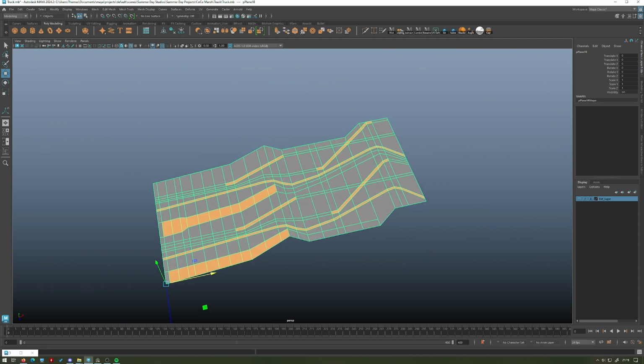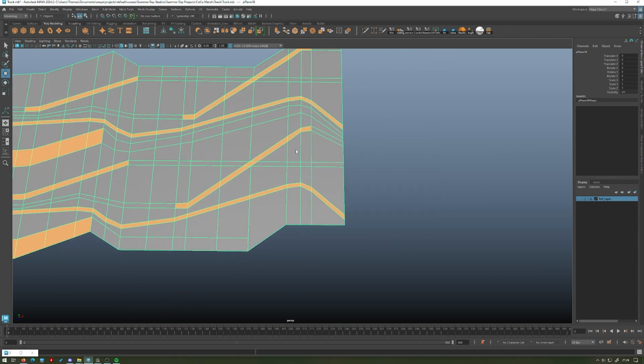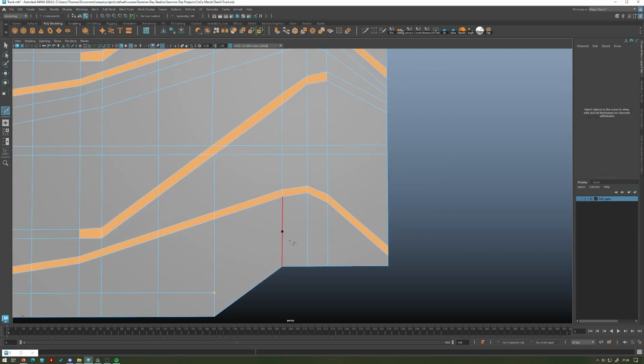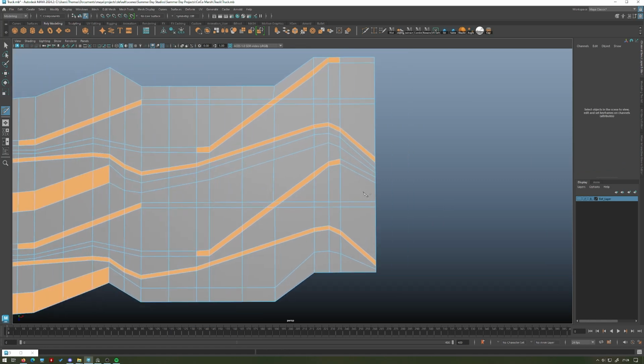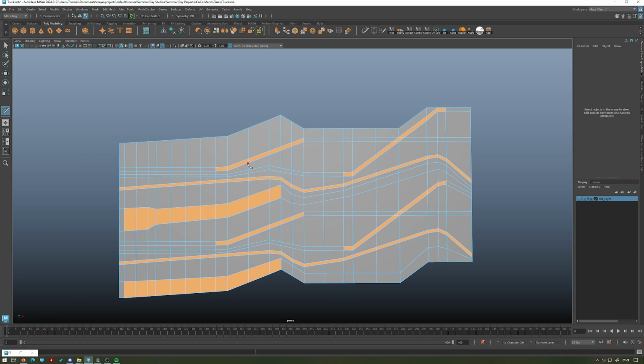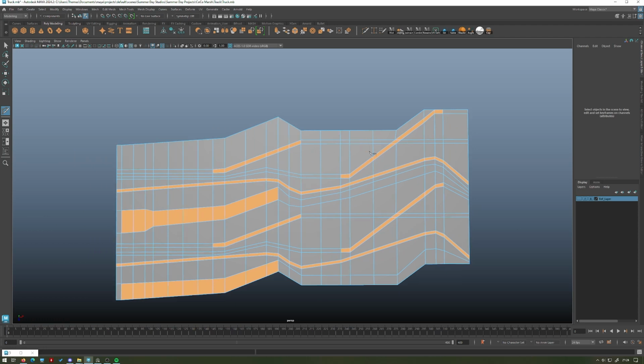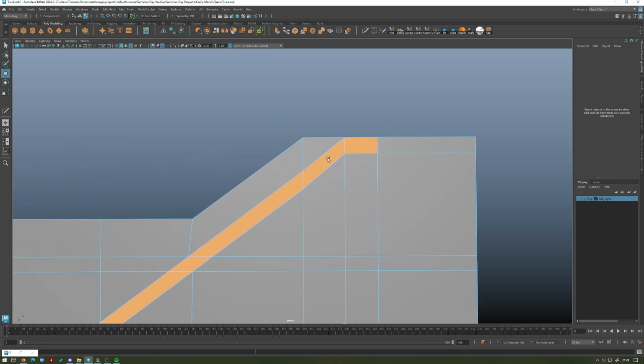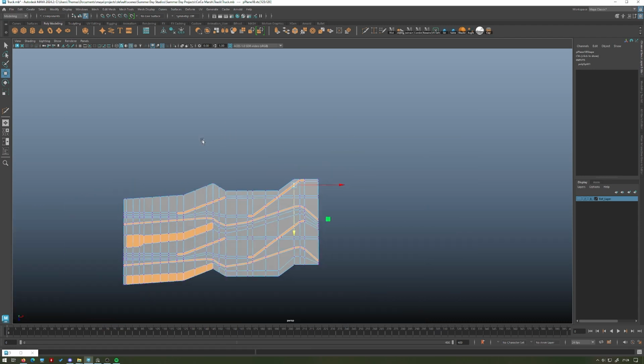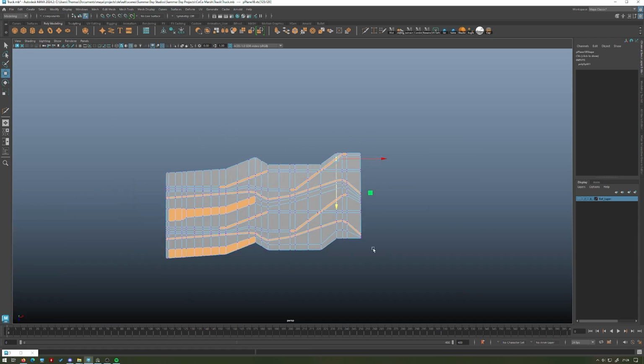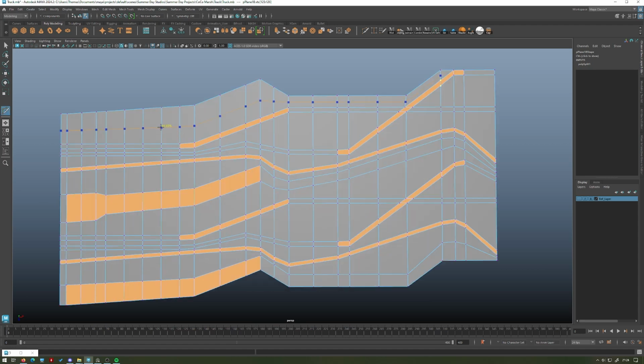Okay, we'll come back to perspective. And now we've got a bit of topology cleanup to do from this kind of bizarre surgery that we just did on our model. So we'll just connect those edges up. I think there was one more, if I'm not mistaken. There's this triangle up here, and this is slightly misshapen, so I'm just going to tweak that. The important thing is we don't want to be editing the outside edge now, unless we're also editing the outside edge here. We could potentially just run an edge along there, and then that solves that problem. And we needed another edge down here anyway. We're getting a bit of extra density here, but I'm not too worried.